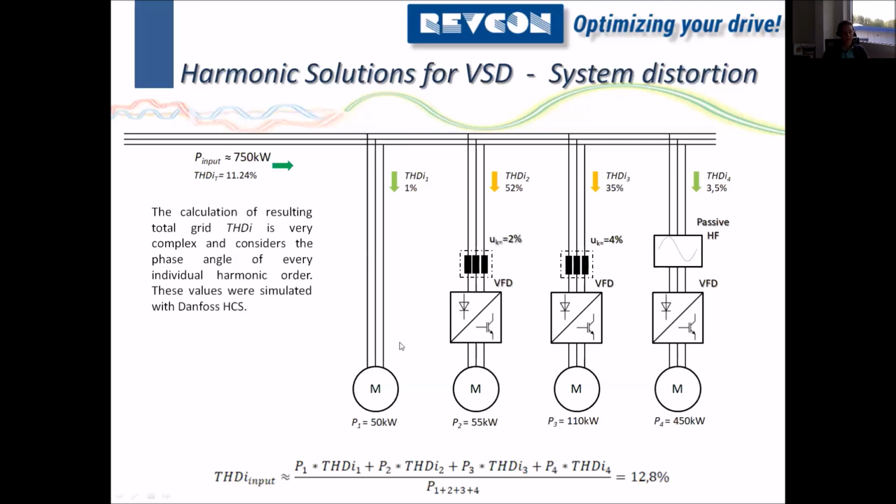It's not an exact science. It's not a scientifically correct calculation, but it is a first way to give you a quick estimation of what kind of result I can expect from the mains. And I think in many, many cases, this will be more than enough to decide, do I need any harmonic mitigation? Do I need any further equipment, or in the worst case, even to size a passive harmonic filter or an active harmonic filter? This can be done with these simplified calculations.